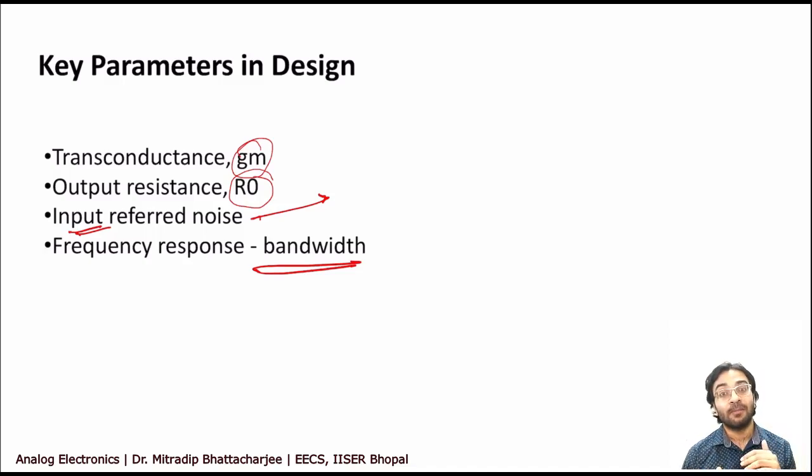One thing you want to increase, for increasing gain, again you have to increase probably gm, which is related to gain. So if you increase gm, you have to increase IC, which is related to biasing. Now if you're increasing IC, you lose power. So it's all interconnected. You can't work on a parameter separately, or keep it isolated and improve it. It won't happen. All of them are related to each other.